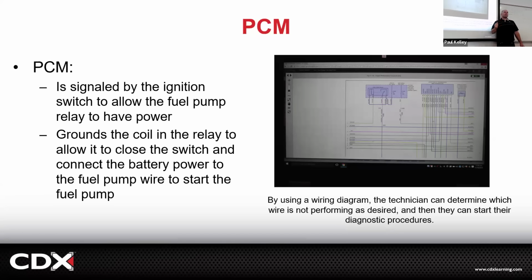If it's got a symptom of a bad fuel pump, like a crank no start, and let's say we put a fuel pressure gauge on it, which I'll show you, and it makes 0 PSI of fuel pressure, you'd say, hey, I don't think the pump is running. You could also listen down in the fuel filler neck and bump the key to crank for a quick second, and you should hear the pump. Or if you keep cranking it, you should hear it, and if you listen and don't hear a thing, you could use a stethoscope.